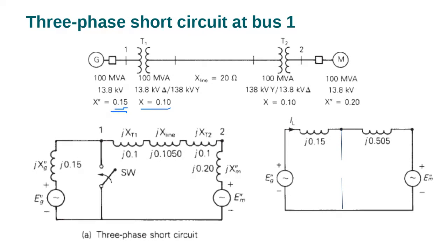Very good. There is no subtransient in transformers. Subtransient comes only from spinning machines. There is nothing spinning in the transformer. Good question here. When you do subtransient, you only do it for a spinning load, a machine. But the transformer has no subtransient. It's just X.